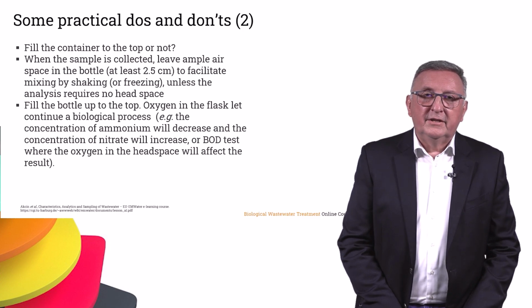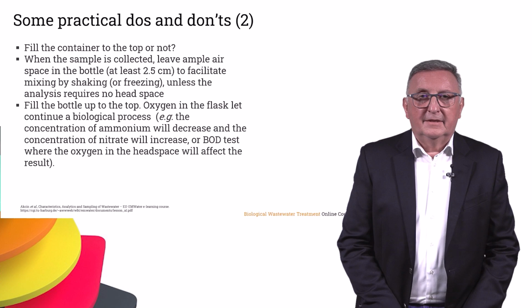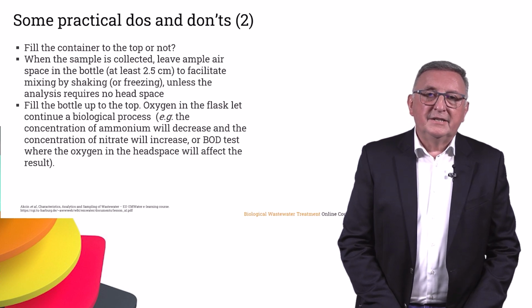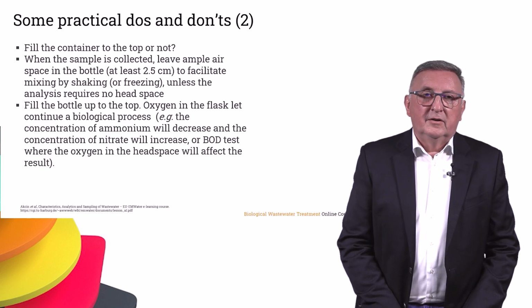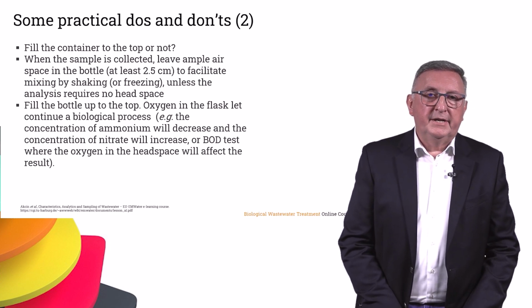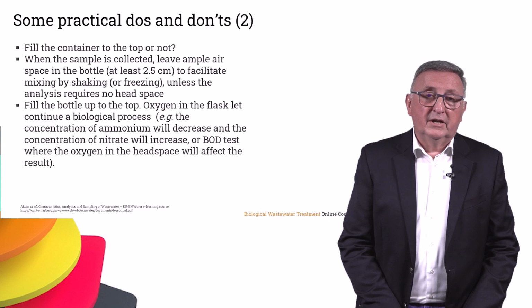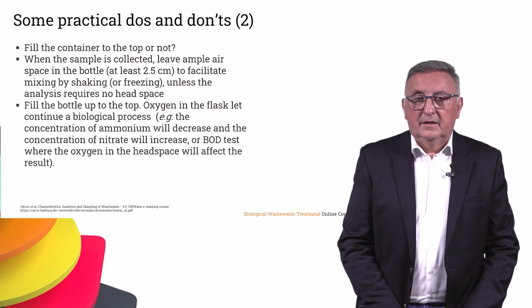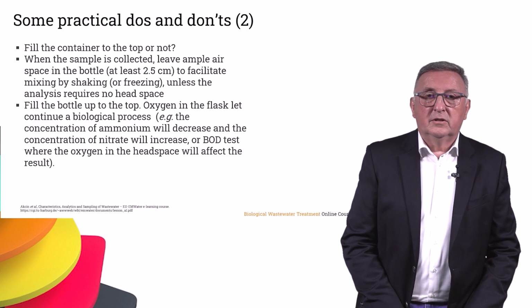Do you need to fill the container to the top or not? That depends on the analysis that you want to perform. For example, when the sample is collected, you can leave ample air space in the bottle, at least 2.5 centimeters, to facilitate mixing by shaking or freezing, unless the analysis requires no headspace. In that case, you need to fill the bottle up to the top,